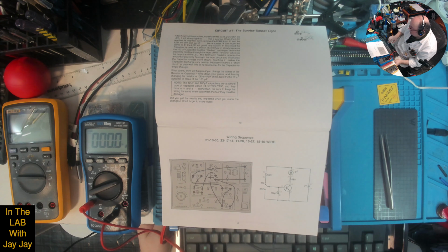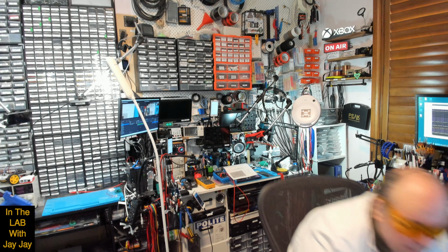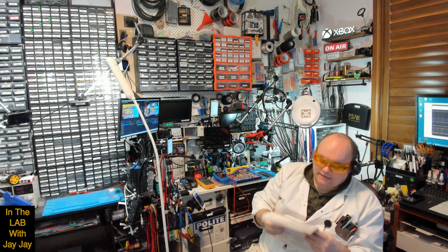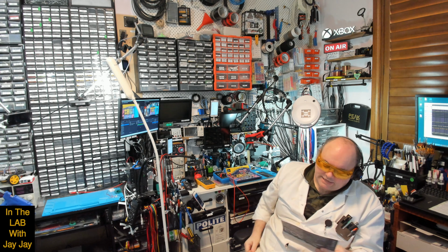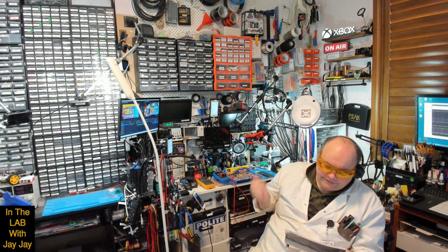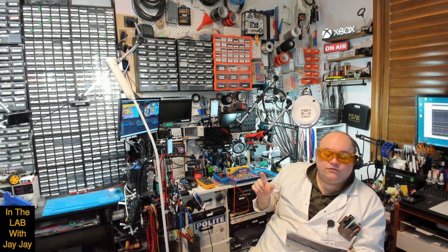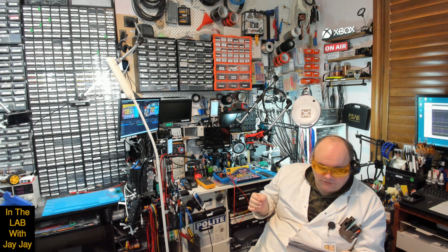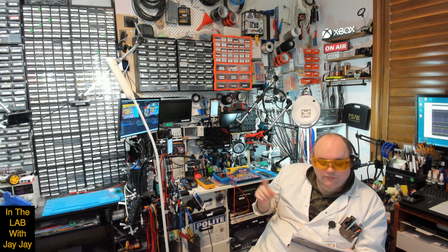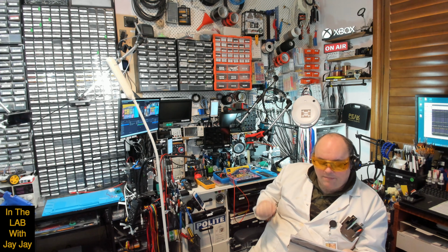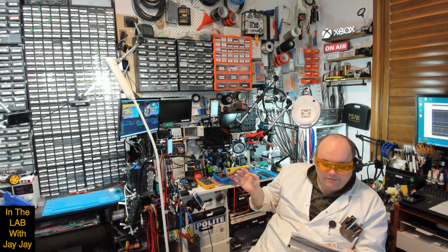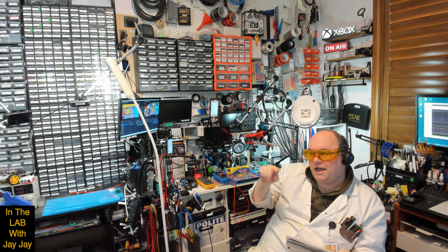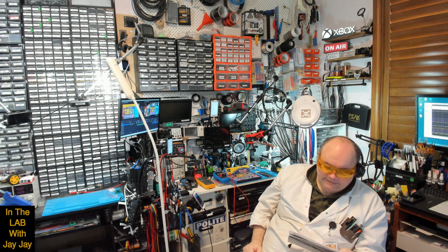So with that, I'll take you over to the farewell cam, we'll wrap up. And that's a wrap. So that was a pretty easy circuit today called the sunrise sunset light. We used the capacitor to control a transistor. We used the transistor to control an LED. When the capacitor was charging, the LED was mostly off. When it was fully charged, the LED went on. And then the capacitor kept it on even when we removed power from the 100K sort of interfacing resistor.